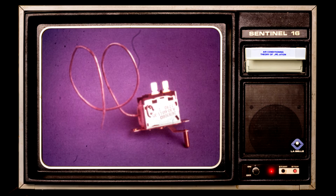This is the air conditioning thermostat, which controls the temperature of the air in the passenger compartment. The thermostat controls the air temperature by regulating the power to the compressor's magnetic clutch. When more cooling is needed, the thermostat passes electricity to the magnetic clutch, the clutch is engaged, and the compressor begins to pump.